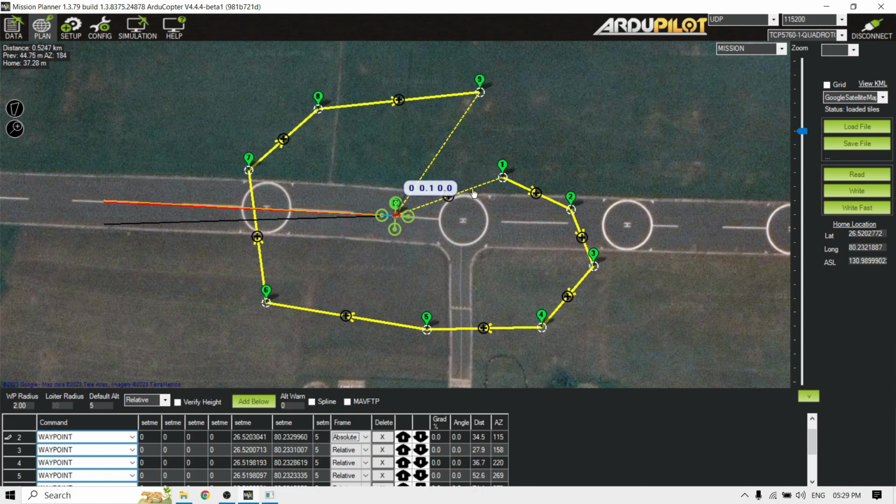Let's assume I'm in the northeast areas or the north part of India, where the altitude is by default very high. If I just give 5 meters and take off, then naturally my drone will never take off, because sea level is much lower, and I'm asking for 5 meters from sea level, and that will not work. So absolute is only for when I know my current altitude from the mean sea level. Otherwise we can keep this relative.